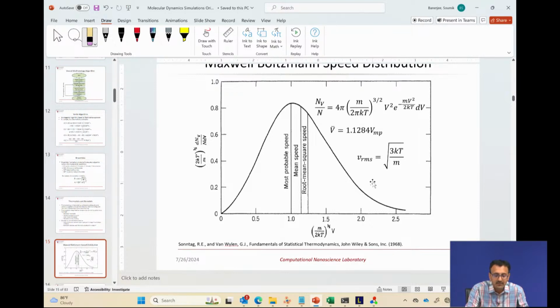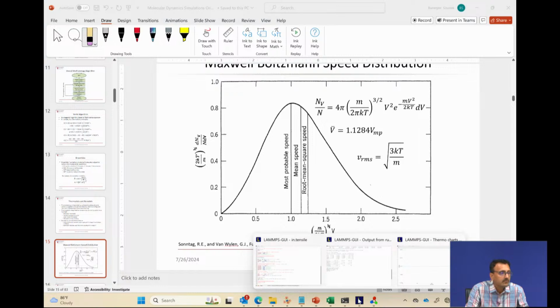In that temperature equilibrium step, why was there a sudden jump at the initial? When the system was initially equilibrating, why did it drop? That's a good question. We started with an initial velocity that was randomly distributed, right? And this is a periodic system. One reason that can happen is an atom near the boundary is periodically interacting with its image, the periodic image of the cell.